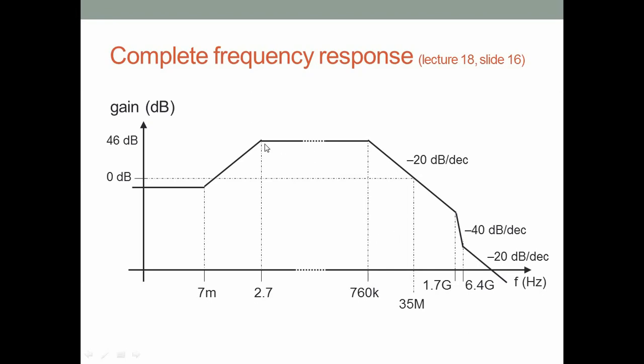If I want to find the lower 3 dB frequency, it is this I'm looking for. So in the low frequency equivalent circuit or the transfer function, and of course there are many frequencies on the lower side, this is the highest of all frequencies. So this is the pn if there are n terms, or it's an nth order polynomial in the low frequency transfer function. All right, so this is an important thing to recognize.